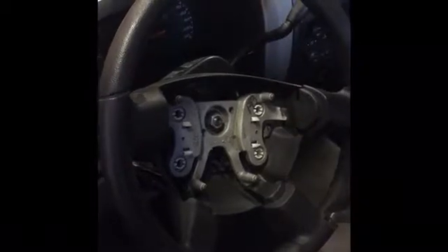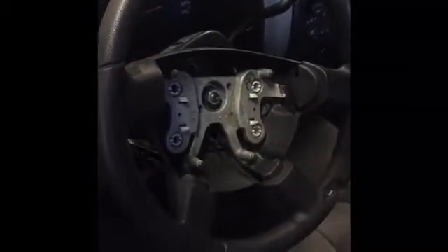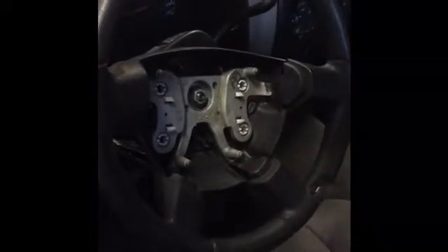There are a series of steering linkages that transfer the effort to the wheels by connecting the steering box to the steering arm on each of the steering knuckles, which also contains the pivots and the ball joint. As you can see, down there is the other half of the steering column, and it runs down to the steering box and the rest of the steering system, which you cannot see at the moment because of the motor and all of the other parts that are in the way. But it is all one system that works together to turn the wheels depending on how far the driver turns the steering.